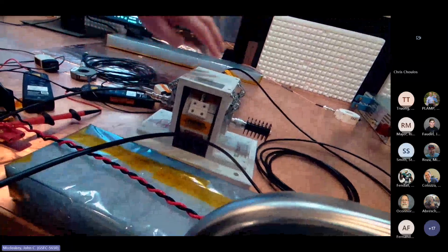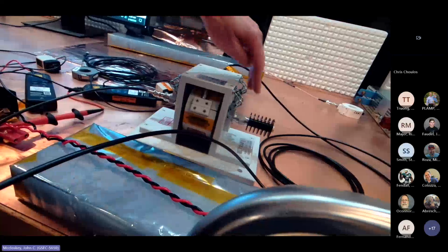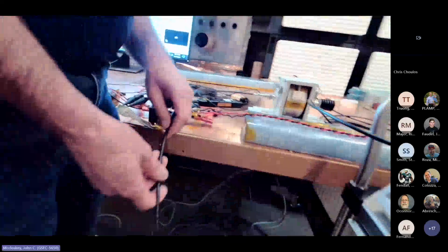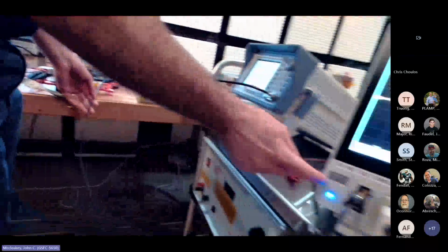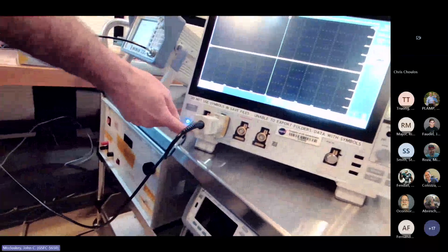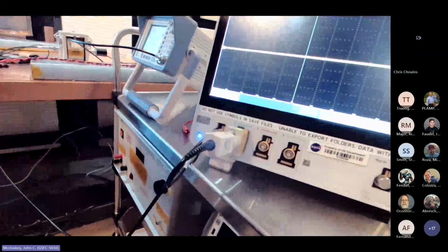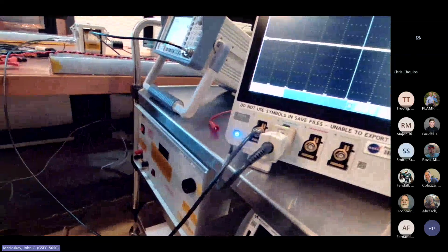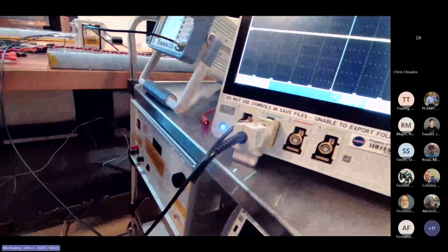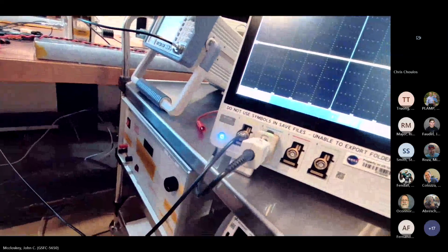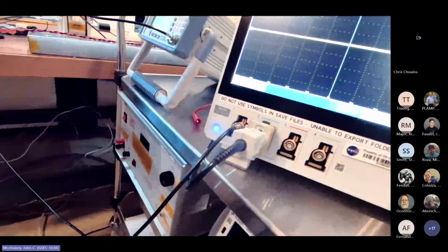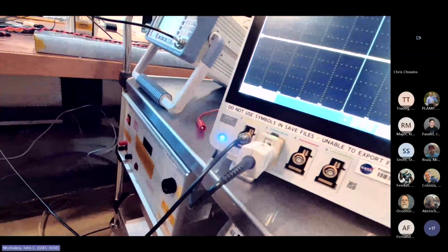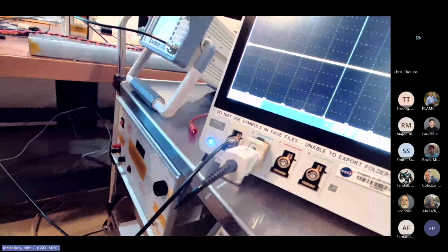So anyway, we got a 50 ohm load here, and then another 50 ohm load coming out ultimately at your measurement device, but it's a 50 ohm input on the scope in this case. You would typically do this, or you certainly have an option to do this, into a spectrum analyzer or even a network analyzer where you could do this sort of thing much more quickly. And I have done that, but I think it's instructive to do this into a scope and really slow things down so that you really see the mechanics of how all this is working.